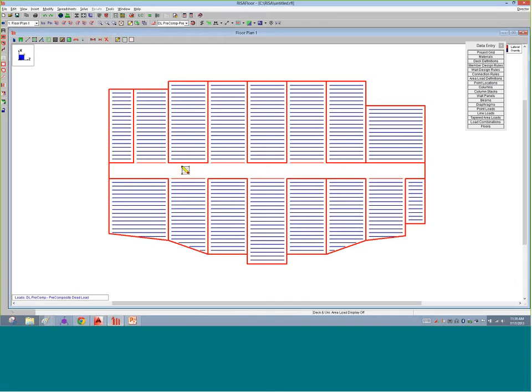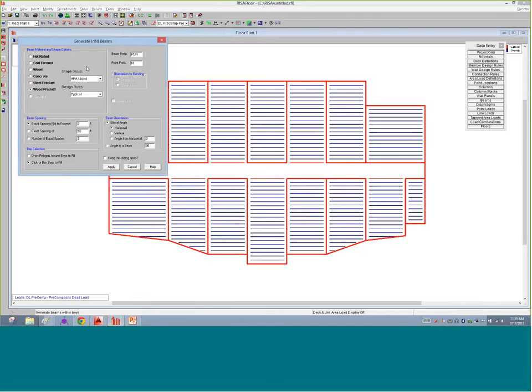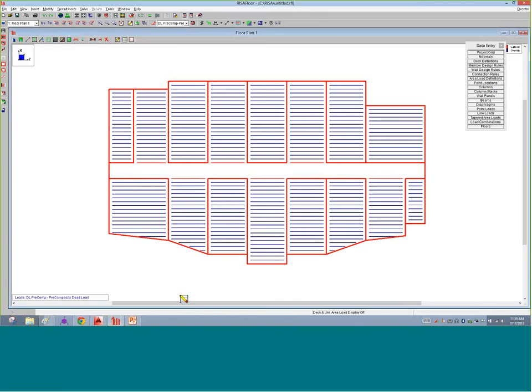For the hallway, I'm going to go vertically. So I'm going to change that. I'm going to go back to that. Probably not I-joist because it's a pretty short span. So I'll pop back into the wood type format and maybe just use a Doug fir. That should be fine for that span. Again, the same 2 feet would be okay, but it's going to go vertical in direction, and I could just click on that. So now I can lay out my whole structure, and it's got all beams.